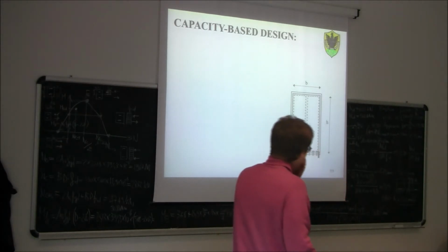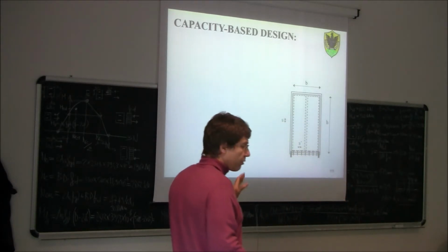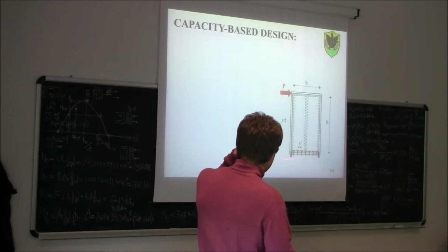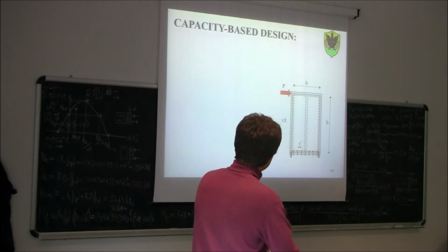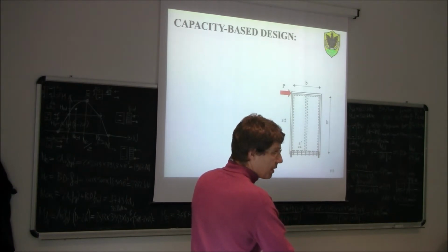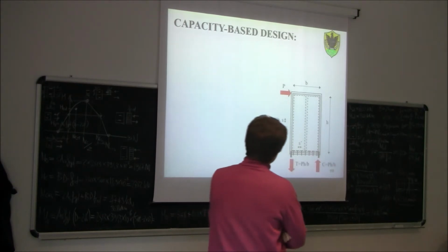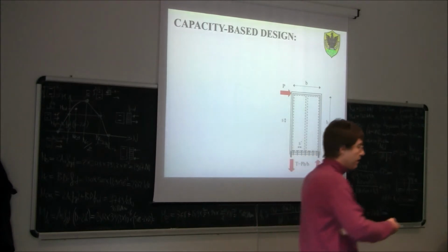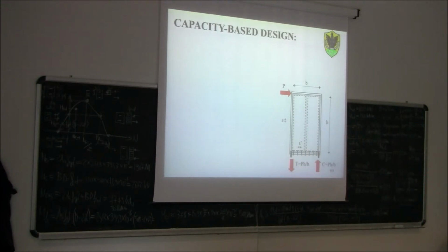So now, how should we calculate those forces using capacity-based design? As I said before, we have a shear wall like this, where we apply a horizontal load P, which is the seismic load. We already said that this wall will act basically as a cantilever.